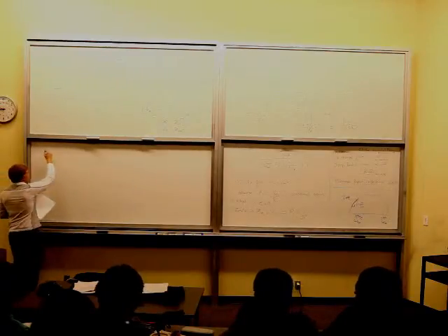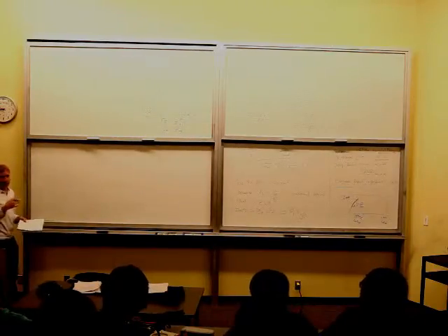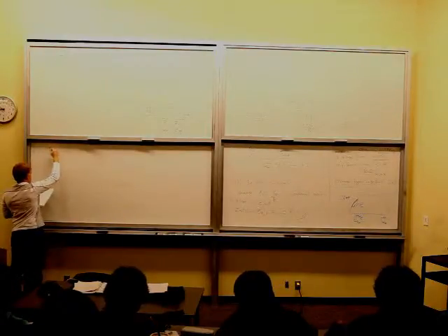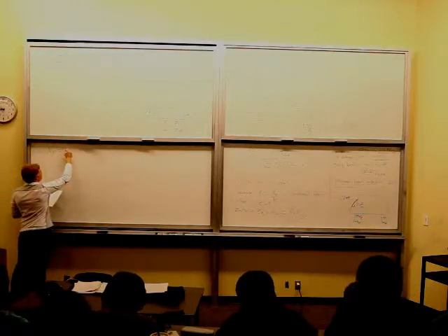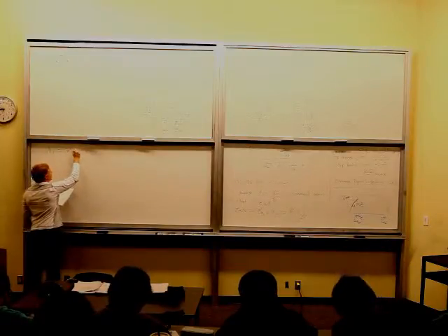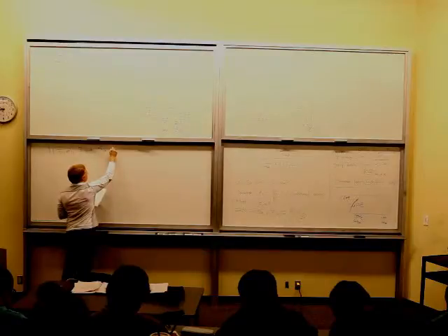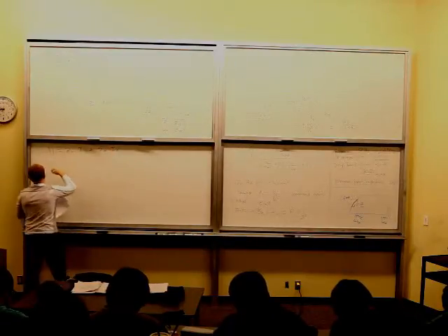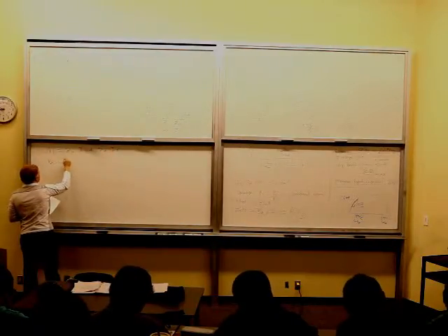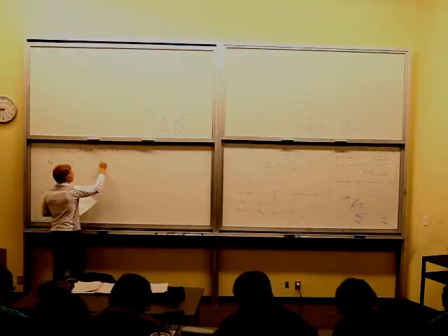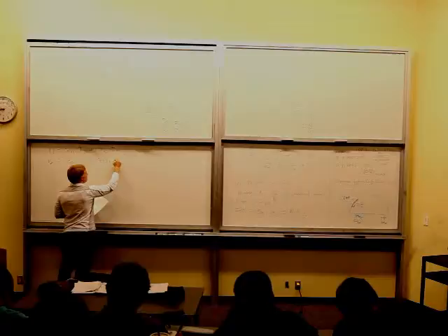So let's actually break these equations out. This is what I was going to say before, is I find it helpful to actually write out those 2 equations in a non-matrix form, so just in an explicit form: V1 equals Z11 times I1 plus Z12 times I2. V2 equals Z21 times I1 plus Z22 times I2.